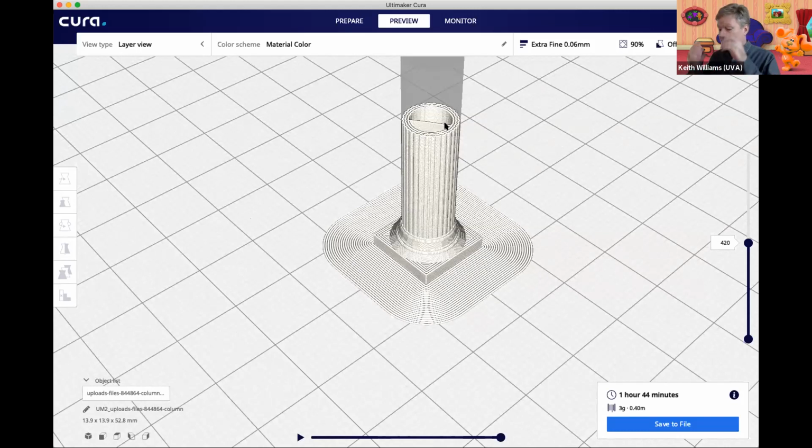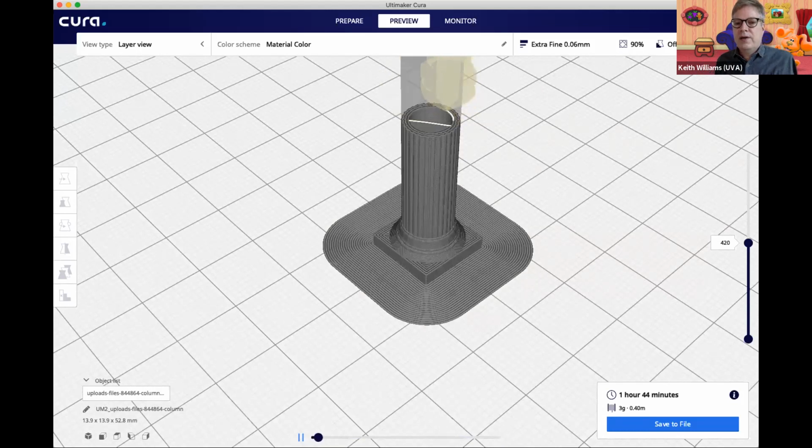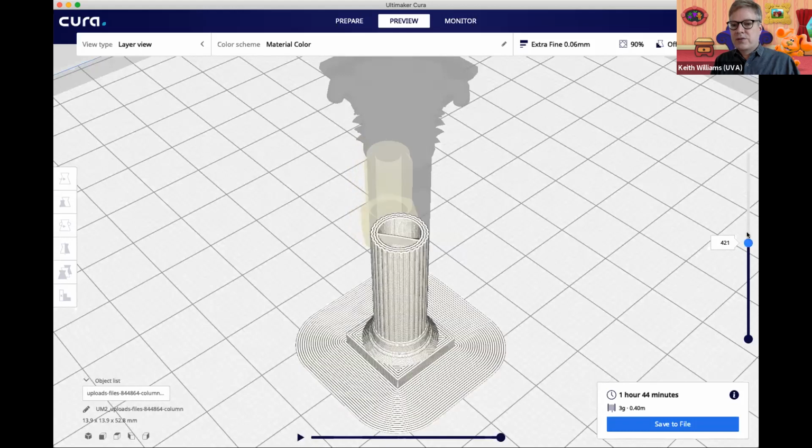This is something really, really special about 3D printing, because as this thing is printing, I could actually fill that void myself. In fact, I can stop the printer at the very top if I want. So let's suppose I get this thing to print almost to the top part, right about there. Do you see where the gyroid fill is kicking in? That's really cool. That's coarse gyroid fill. Now you maybe understand gyroid fill really well, because as I step through the layers, you see how it goes from one direction to another, to another, and then it gets finer and finer.